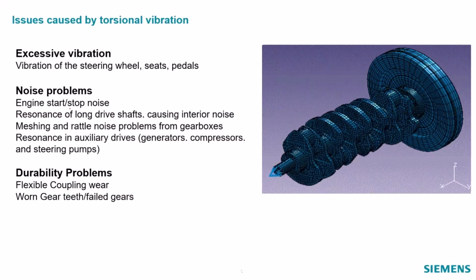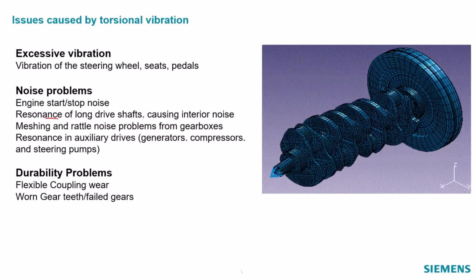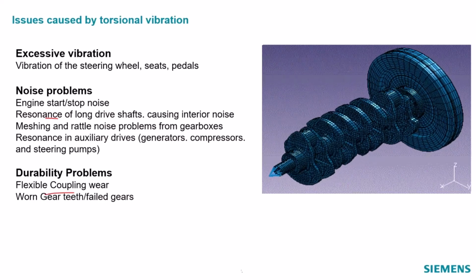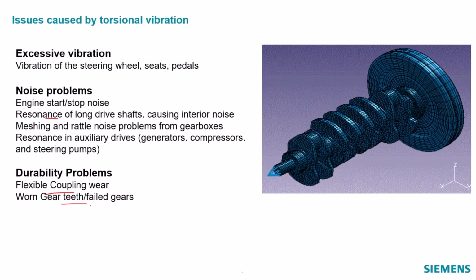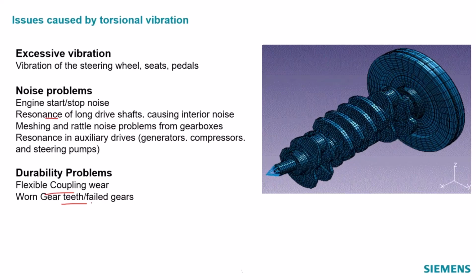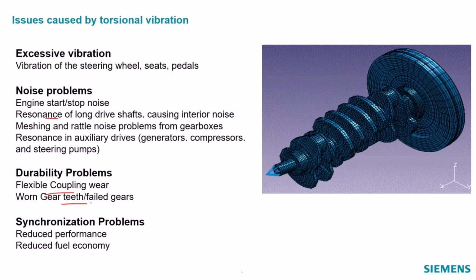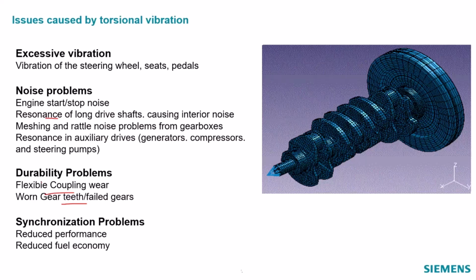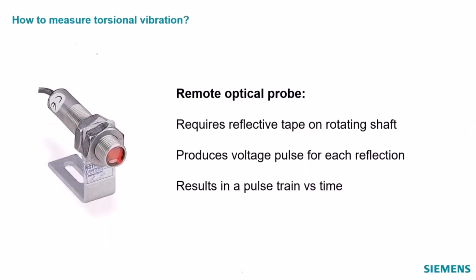For things not to run smoothly, people want to lock up at lower speeds, like on a car, for example, for fuel efficiency. But at lower speeds, the torsional vibration is greater. It's going to wear things out, etc. We need to be able to measure torsional vibration and then hopefully do things to reduce or eliminate it as much as possible. Sounds important. Yeah. All right. How would we measure torsional vibration?